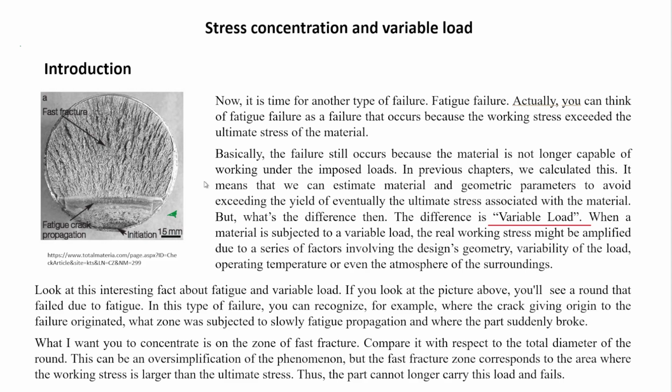And in addition to the variable load, fatigue might also be influenced by other factors that we haven't considered so far, which are, for example, even the size of the part affects the fatigue resistance of the design, and how the load varies. Variable load is not just a characteristic, but the variation itself has an important way of defining that variation.